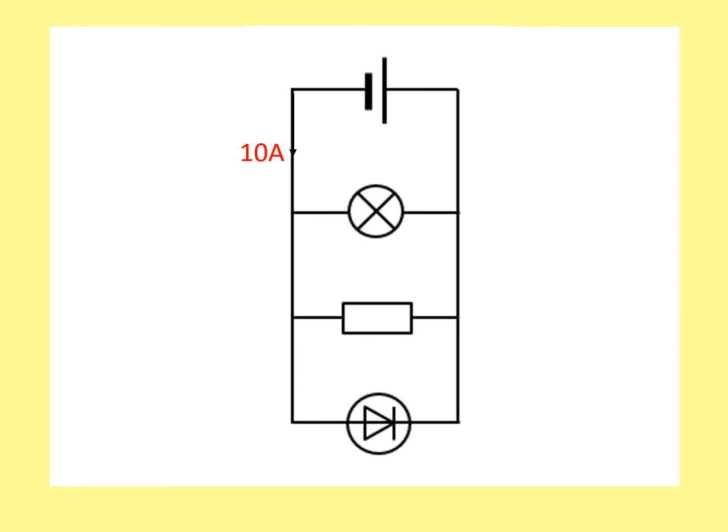Okay, I'm going to do one more example, exactly the same thing. We've got 10 amps flowing down this wire here. So 10 amps going down here. And we come to a junction. Let's just imagine for now that we have 1 amp going off to the light bulb here. This depends on the resistance. Then we're going to have 9 going this way. Now these numbers will get given, or you can calculate using V equals IR. So the more resistance that this bulb has, the less current it would have.